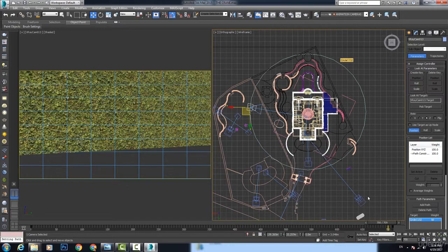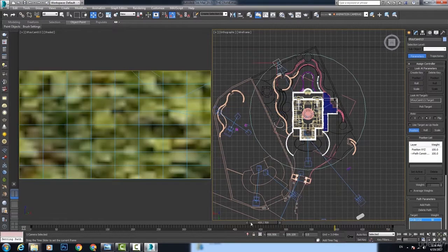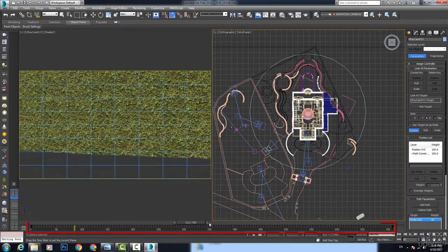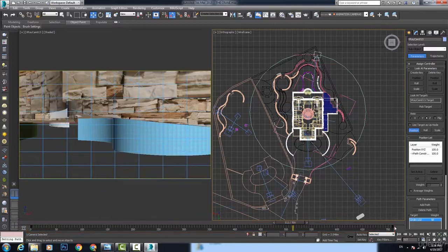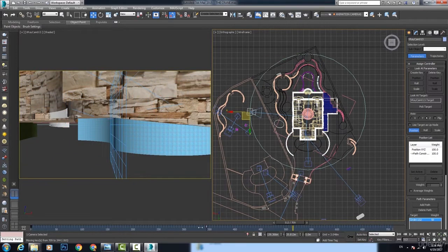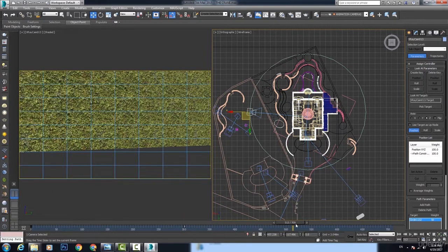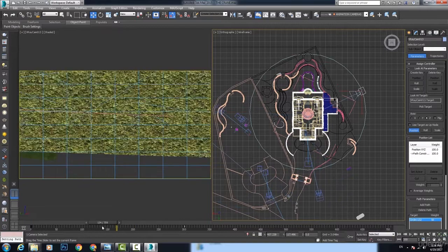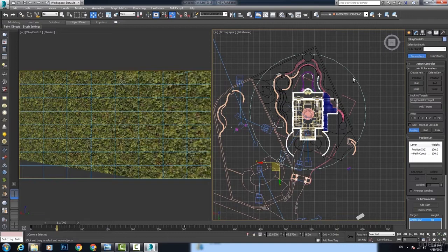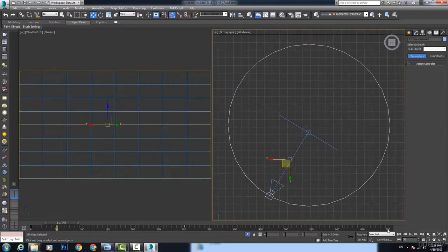Max automatically created an animation for our camera following the path of the circle in the 700 frames of our timeline. If we only want 300 frames for this camera, simply we can move that keyframe at 700 to frame 300. Now the camera will rotate at 360 degrees around our building in 300 frames. Let's select the camera and the circle and isolate for better view.